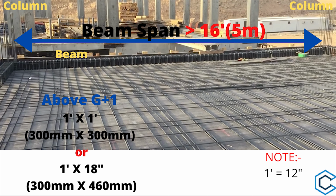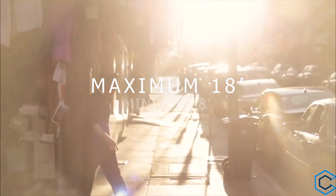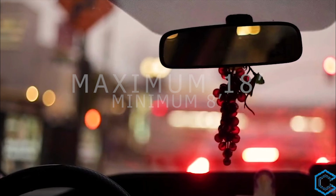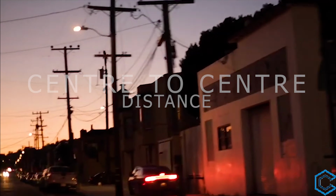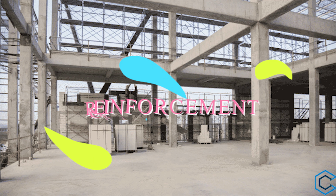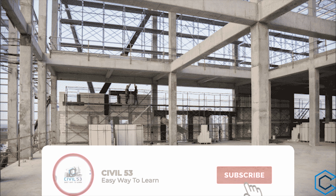For buildings having beam span greater than 16 feet above G+1, we should use a 1 feet by 1 feet column at the outer periphery of the house and a 1 feet by 18-inch column at the center location where there is accumulation of large amounts of loads. For achieving an economical design, we should place columns at maximum 18 feet, minimum 8 feet. As the center to center distance between the columns increases beyond 18 feet, it will start asking for bigger size columns and large reinforcement.